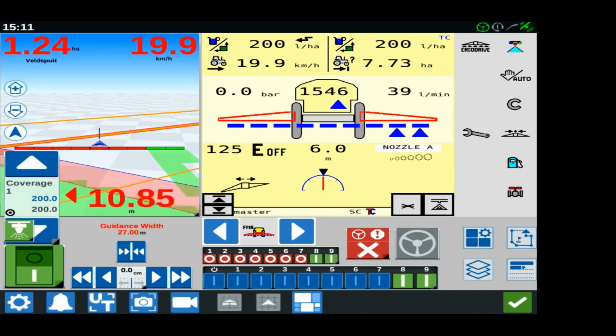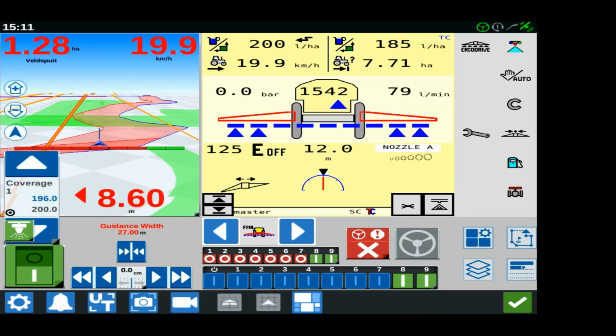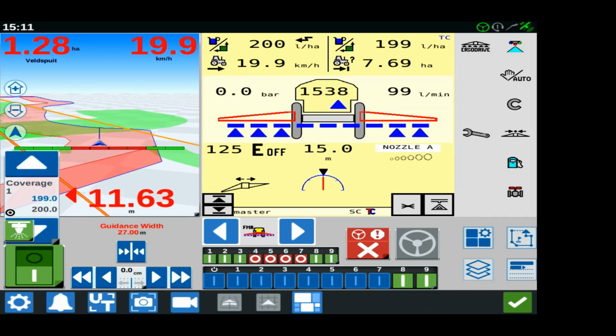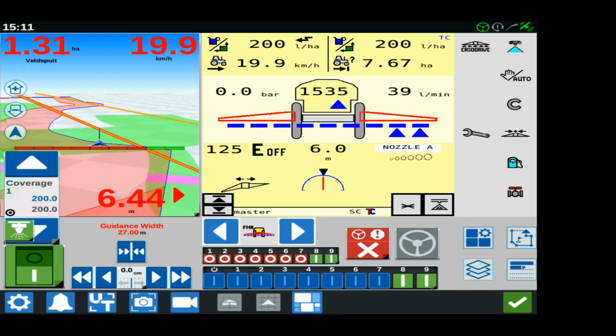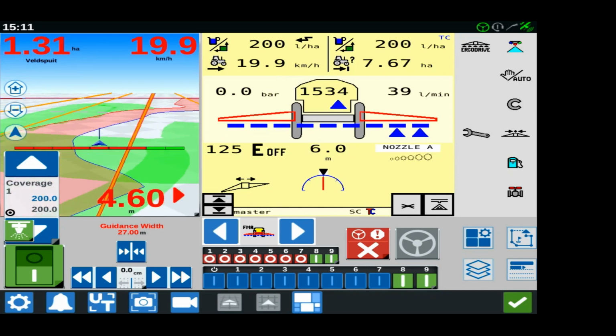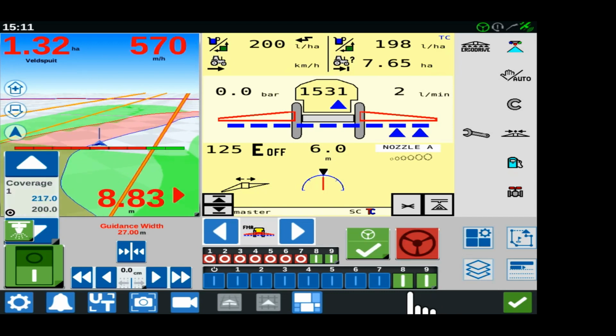So now, I'm not as good a driver at the moment, but now I would be able to drive on the side of my field boundary and spray a little bit on my neighboring field as well if I want to. So there are also some options in manually overruling the section control. Make sure you put it back to blue again if you want to do it automatically.